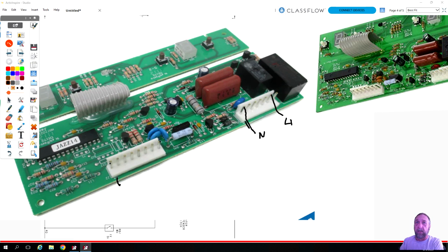Well, it's alligator clips or small pin connectors, because even though this connects to the board, I don't really want this thing moving like this, touching other pins, because it could damage something. In this case, I'm not too concerned about it. And the neutral here fits on there, but they're loose, and this thing could come off real easy. If I had the smaller connectors, it'd be nice to have a connector that just fits right on the pins that I want. So I'm gonna check. I put power there to pin 1 and 6. I'm gonna turn it so you guys can see it, and I'm gonna turn on my power strip, and nothing lights up.